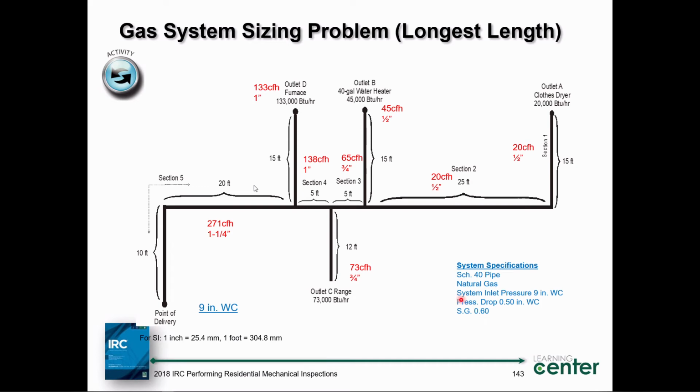The specific gravity means it's in relationship to air in a laboratory at 86 degrees Fahrenheit. They compare the gas weight to normal air, atmospheric air. I believe it's at like 60 or 50% relative humidity. And that is the comparison. They call it specific gravity of gas. So I call up the utility. I say, hey, what's the specific gravity of gas in your jurisdiction? The engineer says, well, we got a specific gravity of 0.6. I say, great. I got all the information I need.